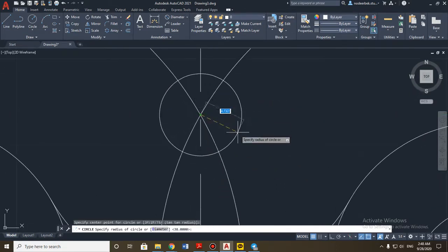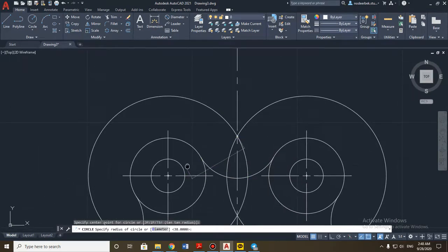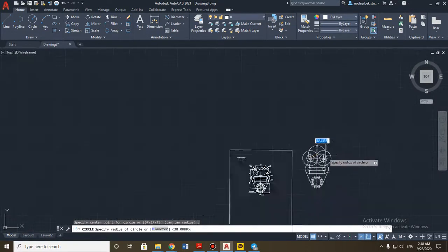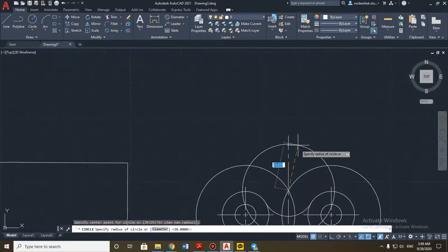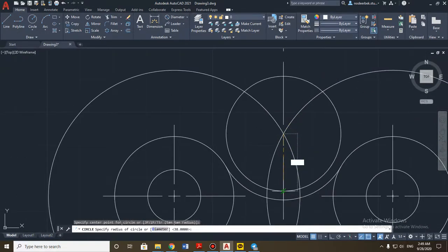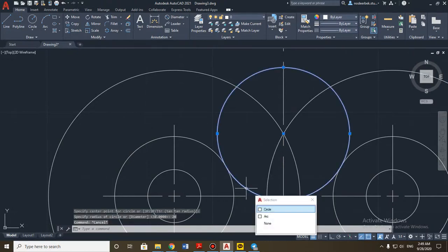I will do it like this, and then build another circle with radius, as you mentioned, here the radius was 20. So if I put 20 here, it lies exactly on the curvy line also. Done. As you can see, this small curvy line stays in the same position.